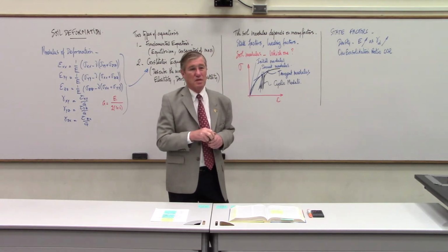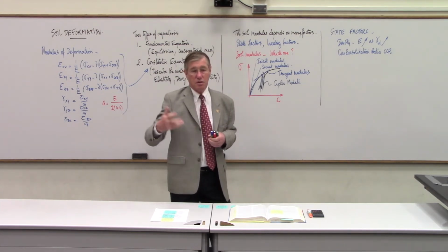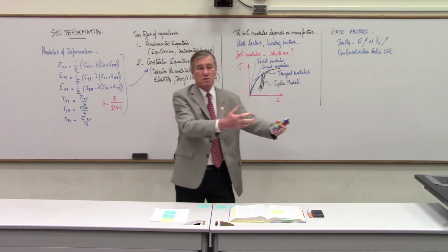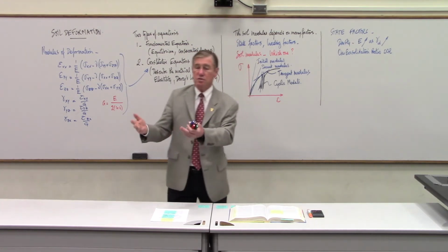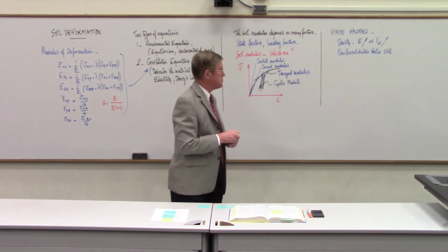Essentially the soil in Chicago is pre-stressed, the term that we use in concrete. The soil is pre-stressed or over-consolidated. Pre-stressed is the word we use in concrete, over-consolidated is the word we use in geotechnical engineering.